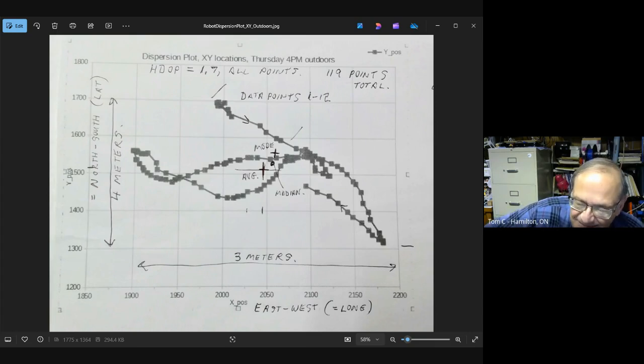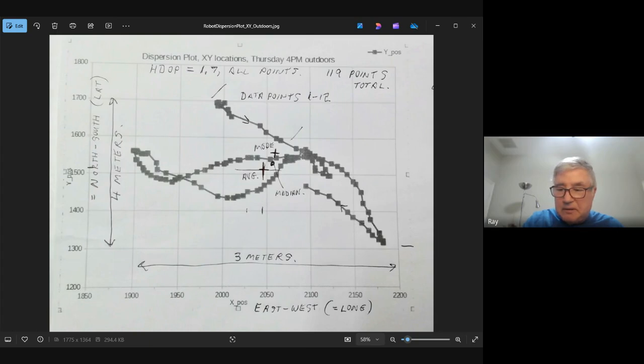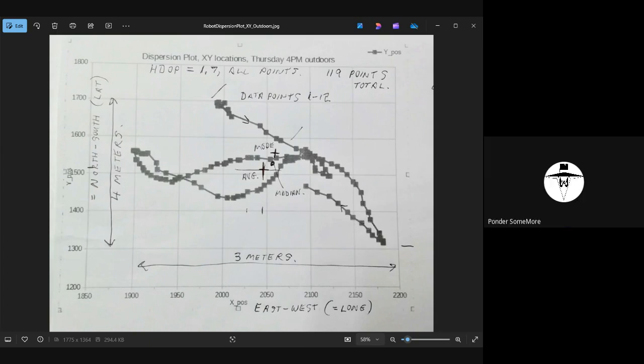Yeah, I think the F9s actually have a powered antenna, don't they? Well, they're powered through the coax cable. Yes. Right. So the antennas do draw power. Yep. But they are active. And if you don't supply enough power to your module, you'll sort of be sadly out of luck.